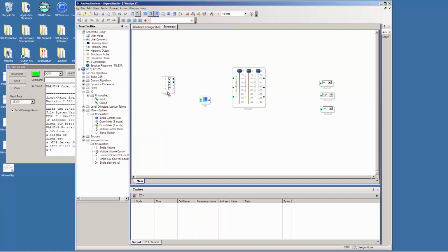What this signal mixer will allow us to do is take both the left and right channels and combine them into one signal. Another thing we need to do to implement that is to put a T connection in. That allows us to do the original split. So I have 2 of those, and I'll connect these to our left and right inputs.